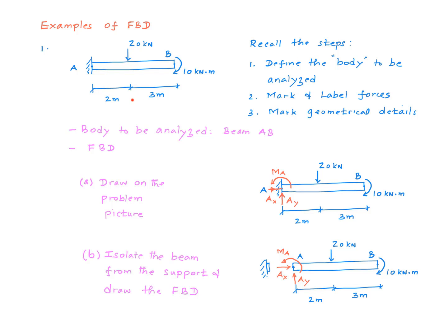So as we go from the problem picture, all we had to do was to mark the support reactions and label them. So this is a fixed support, therefore we're going to have two force components, AX in the horizontal direction, AY in the vertical direction, and a moment MA.